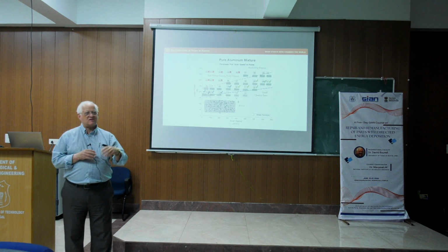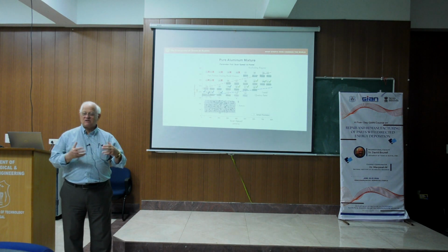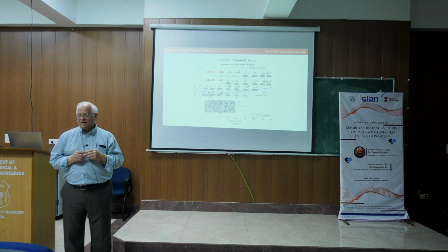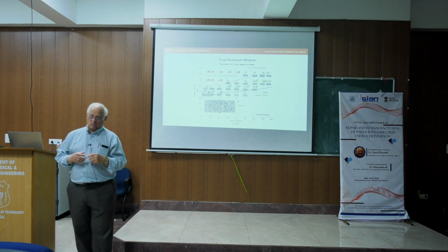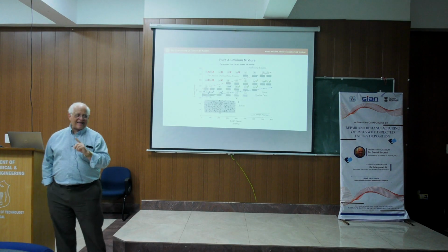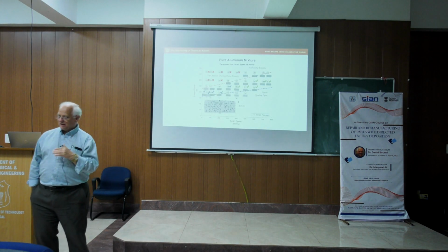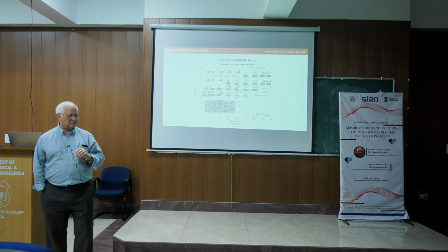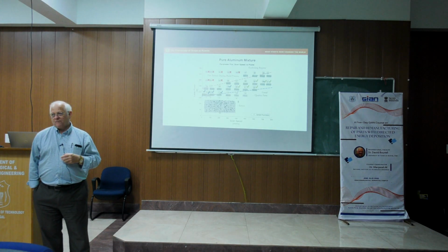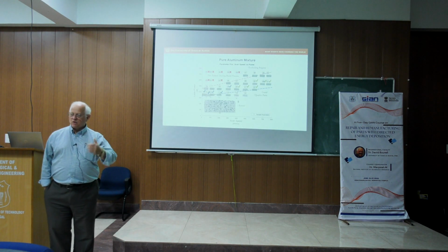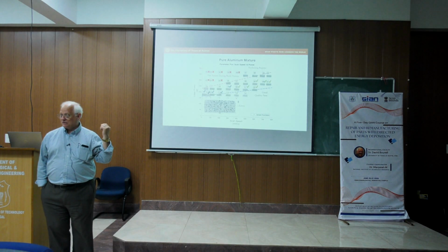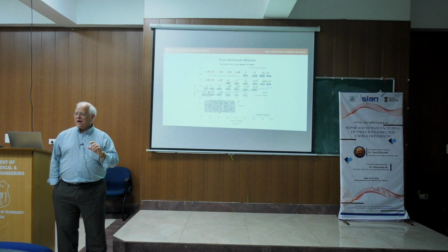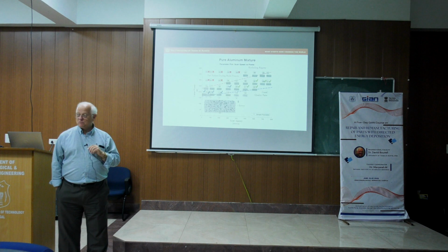Other manufacturing processes, like casting processes or additive manufacturing, all typically are less reliable in terms of defect structures, microstructures, and performance. The way that ties into this question of anisotropy is that if you look at the deformation processing literature, you look at rolling or at raw materials, the materials that we always compare additive to, the raw metals. If you look at those, the question is, how reliable are the mechanical properties of those materials?